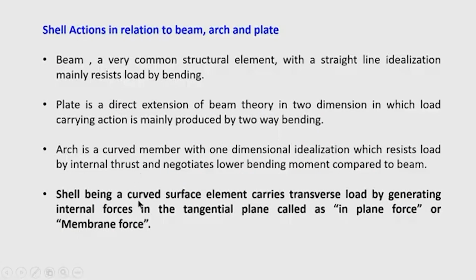So, in relation to this, a shell can be treated as a curved surface, because an arch is a line element, a beam is a line element, but a plate is a surface element. So, the improved version of a plate is a shell. A shell, being a curved surface element, carries transverse load by generating internal forces in the tangential plane, called in-plane forces or membrane forces.